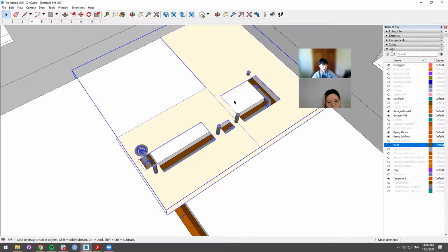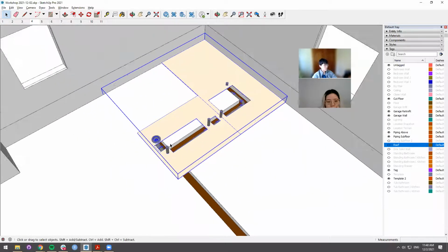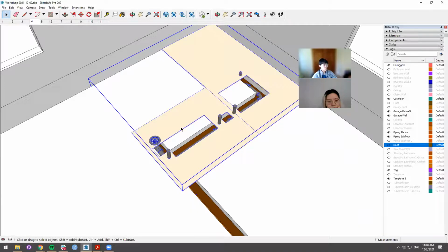In theory, we think you could also do a pressure test on just this component. And you might want to do that right when you've brought it in, but you haven't put back in aggregate and concrete. You would plug at some lower level here, and then you would plug these apertures and do a kind of pressure test or water test. That would potentially be all that's necessary for the inspector to say, that plumbing system looks good, and then we'll come back to see your above floor plumbing pressure test. But it would give the contractor the confidence to then fill this up.